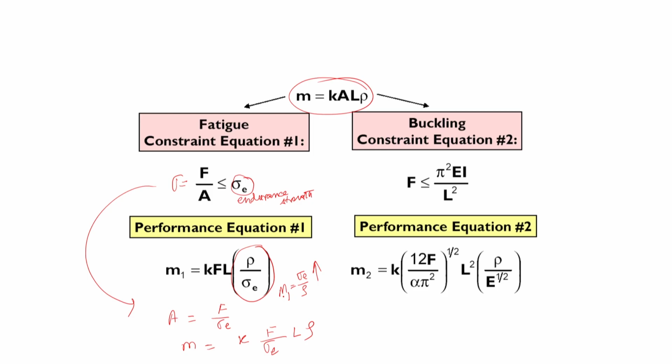M1, the first property. Okay. The second one, you can do the same way I have done earlier for that circular beam. Only a small change is that the I here need not be exactly circular. So, the I generally we take as pi r to the power 4 by 4, right. Instead of that we will take it approximately, keeping a factor alpha, as pi square by 12 r to the power 4.